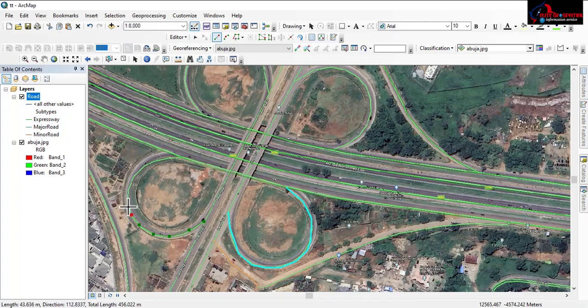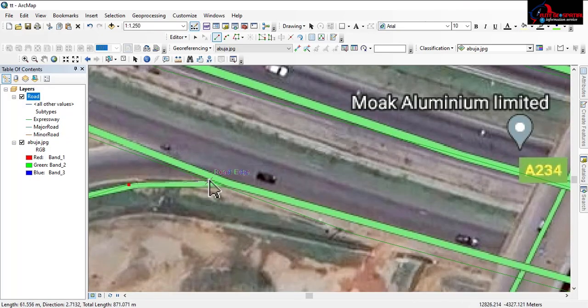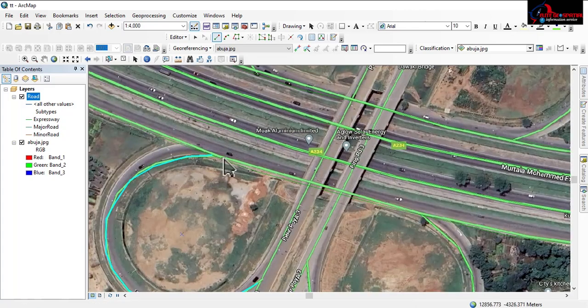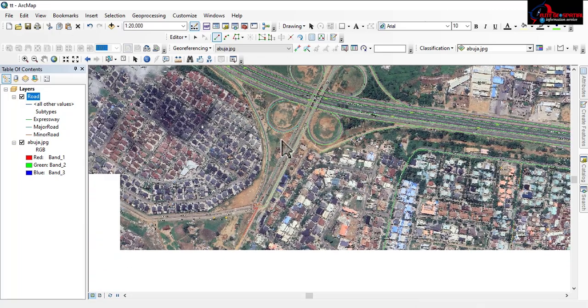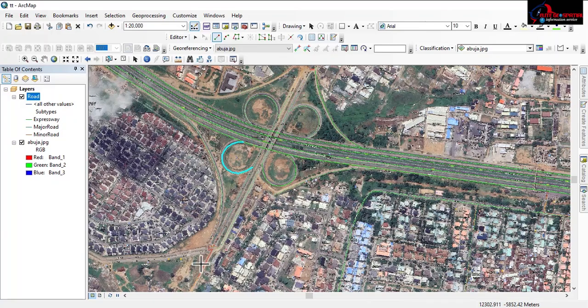So you look, direction is very important, right? So when you meet a digitized road, you must create a node. Let me zoom it so that you see what I'm saying. Creating a node, you must end it on an edge. Double click on it so that the road does not hang. Now, this direction we have whereby this road, we did like this, right? So this road is going like this and this one is coming like this.